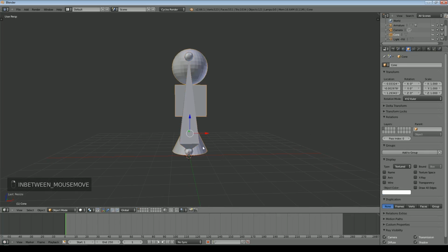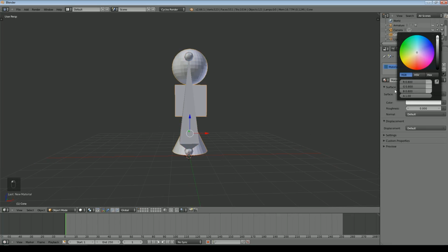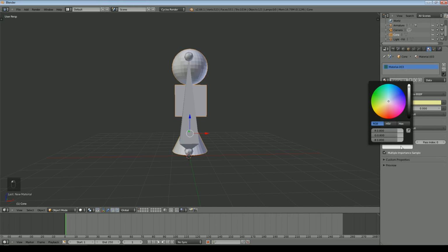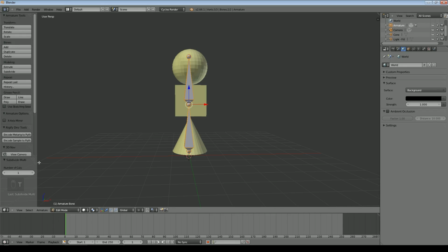I think what I'll also do is I'll add some colour to that object just to make it a little easier to see. Right. So with my bone selected, go into edit mode, press W and subdivide, and we'll go one more on the subdivision. So effectively I've now got 3 bones.